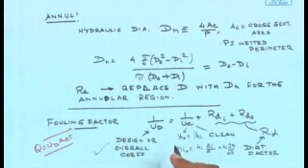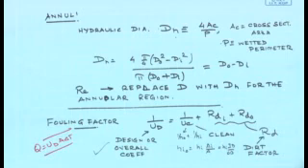Now, remember that in the case of double pipe heat exchangers, there is no need to calculate the correction factor F for LMTD, because for double pipe heat exchangers it is either purely counter flow or purely parallel flow. There is no question of mixed flow for the case of double pipe heat exchangers. So, the only thing which remains right now is to calculate the pressure drop